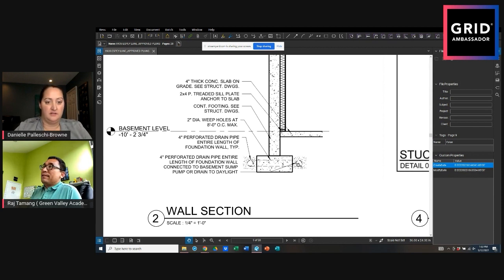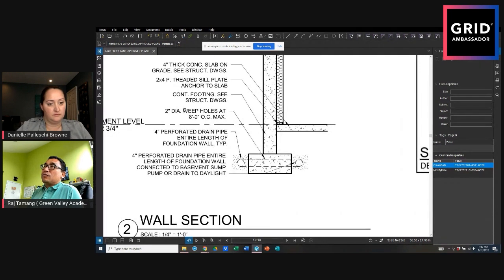One trick I've seen many times is with these weep holes. If you don't put the weep holes in correctly, you collect the water, but there are no weep holes, so how are you going to take it inside? You're in trouble now. This is only a 2-inch PVC pipe. If you are not careful when you pour the slab, you can easily block the hole, clog it.